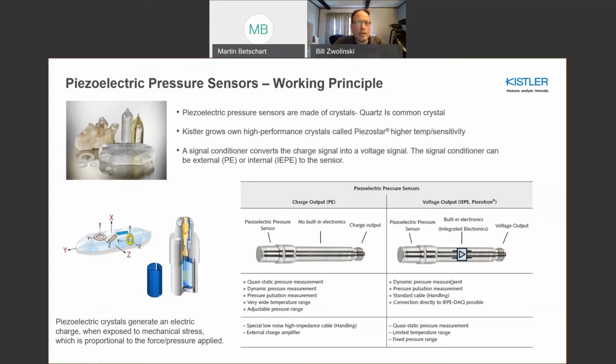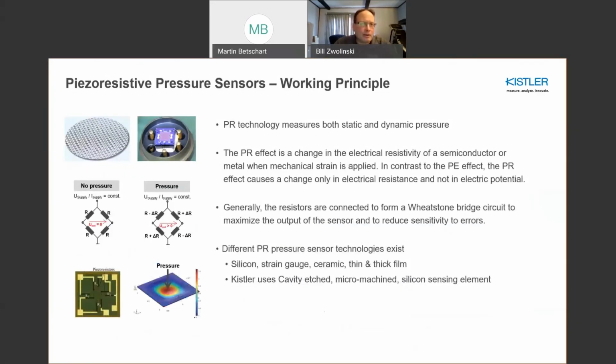So, making the proper choice often requires just a bit of a talk with your favorite application engineer, and you can dial in the right solution. We also have piezo-resistive measurement solutions. Piezo-resistive solutions operate in a flexure design, where you actually change the resistance of this bridge, and that resistance change is proportional to pressure, and it's all calibrated in a very precise manner.